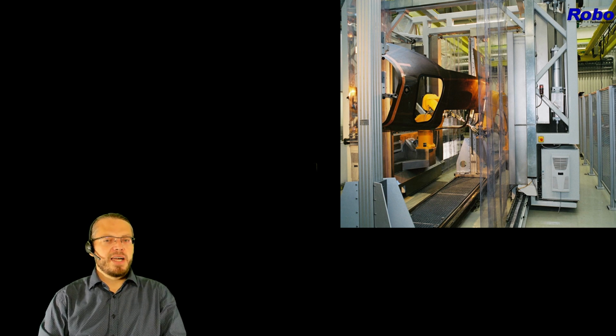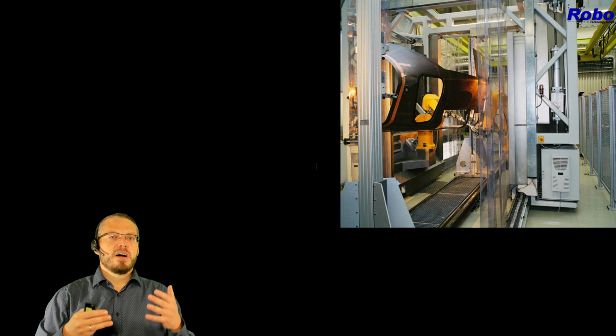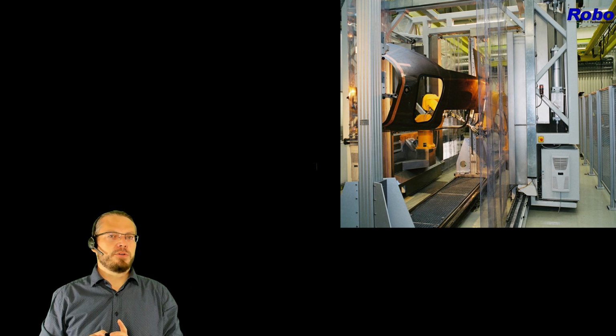Now, coming back to the beginning, the ultrasonic instruments still use an index and a scan axis. But now we are positioning our probes completely in a 3-dimensional space. We are also rotating our probes. So in total, each of those robots has about 6 dimensions. At this point, it might make sense to go away from a 2-dimensional encoder system to something like a 6-dimensional encoder system.